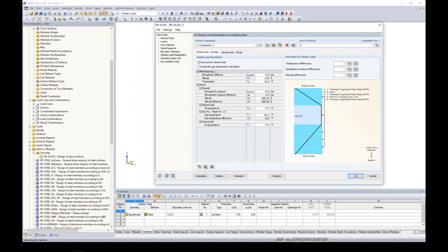So with this unchecked, I think these are pretty straightforward, which is nice. The first thing it's asking us is, where is this glass panel manufactured? The atmospheric pressure is default 14.9, that's fine. Let's say this glass panel was created at sea level, so we will automatically put in our altitude of 0 here. The temperature, let's say it's something more like 65 degrees.